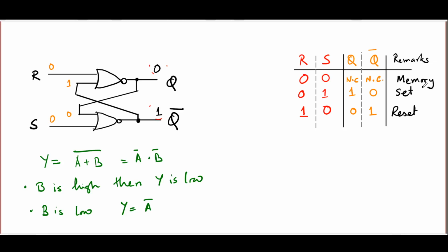Let us now come to the last of the 4 possible input combinations, the one which I have not mentioned so far. What happens if R and S are both set to 1? Now this condition is called race, and if you look at a standard textbook, you will find that the outputs are not even marked in this case. In most textbooks, they are just labeled with a star, implying that there is something crazy going on here.